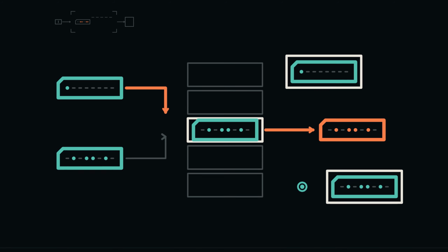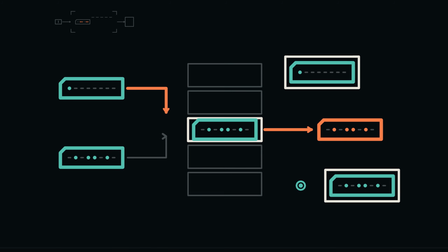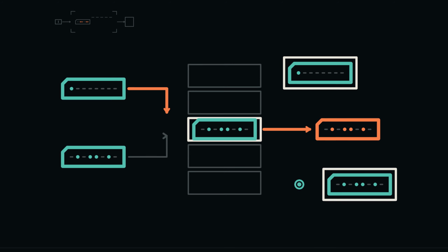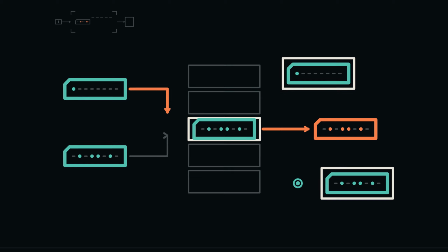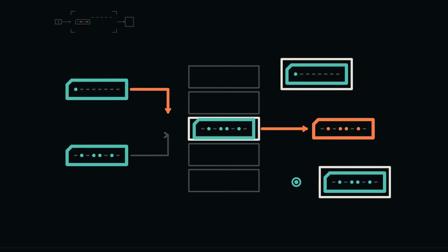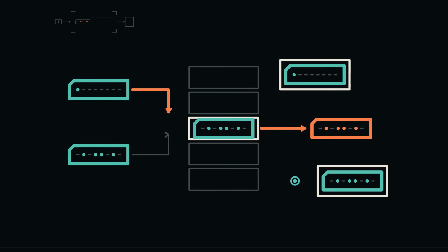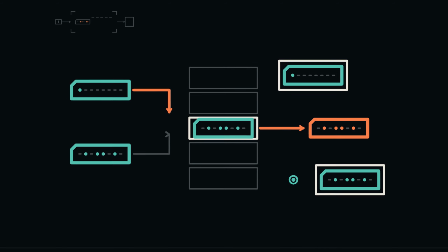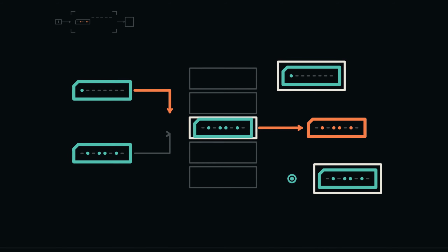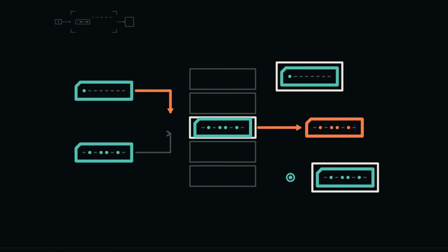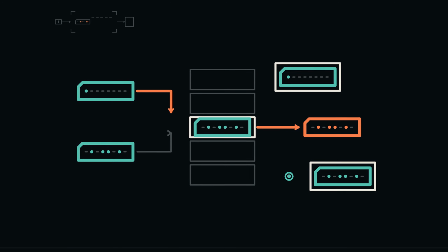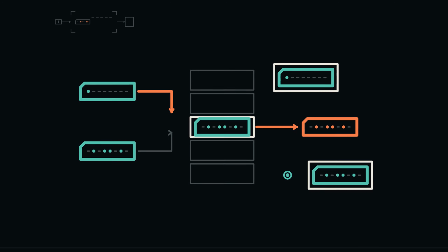Predict the states immediately before that edge. Memory 80 is 5A, MDR is 5A, and the destination still holds its old byte. Immediately after, the destination is 5A, while memory and MDR remain unchanged. A memory read may therefore involve address, read capture, and consume. Compressing all three into the word load is convenient only after these transfers have been earned.